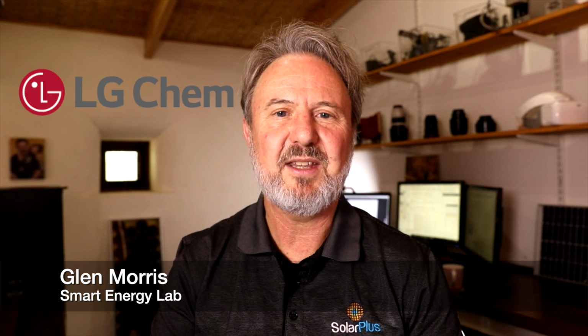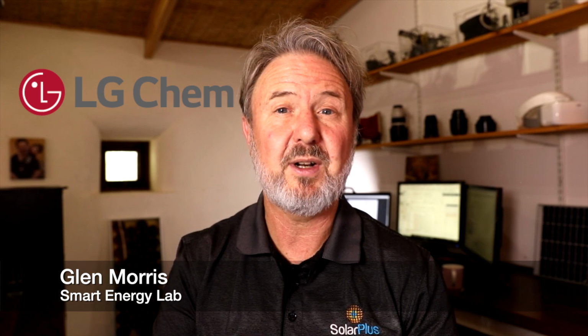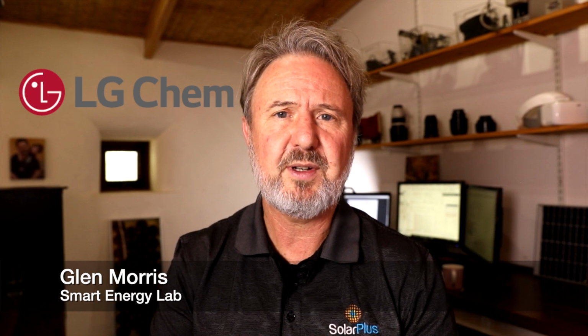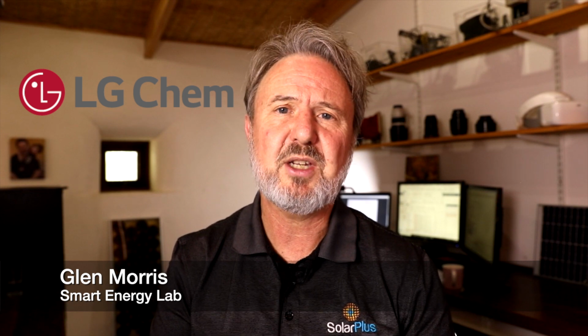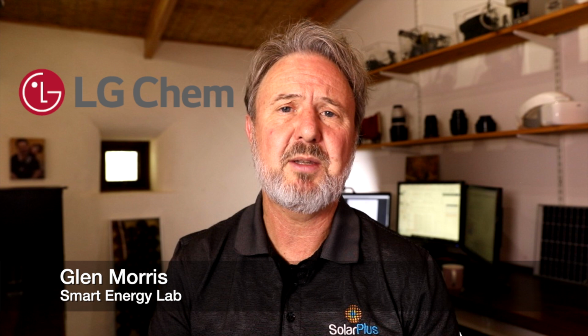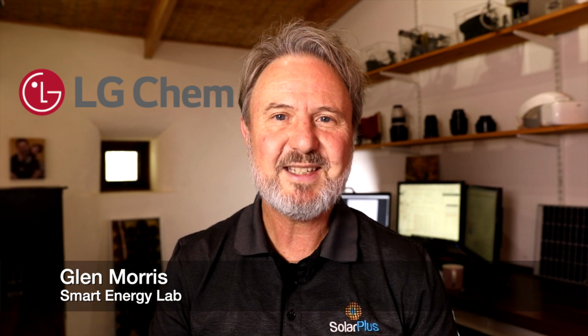Today we're going to be looking at things such as calculating the VA maximum demand for an inverter for a standalone power system and understanding load profiles and how that can help us size a system. Also looking at string over current protection, mismatched arrays on the same MPPT, and how we calculate the maximum voltage of a PV array under cold conditions. All right, let's get into it.